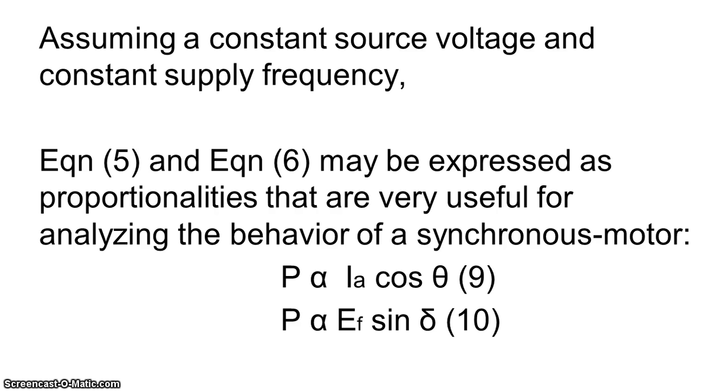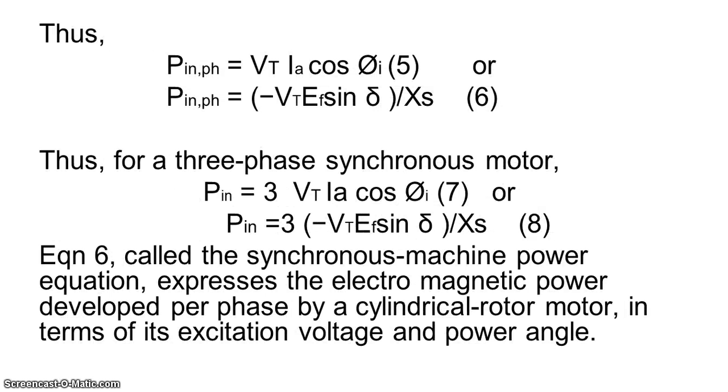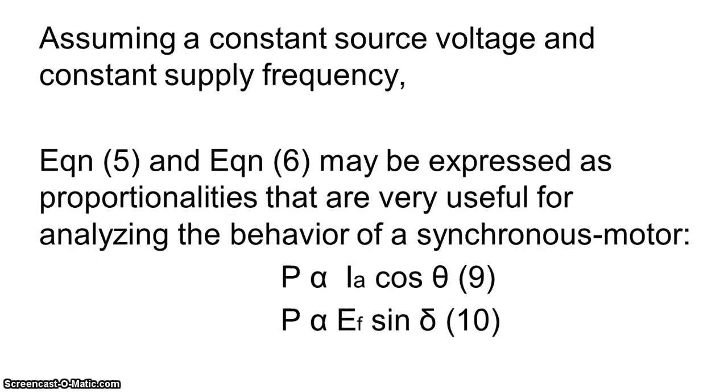So assuming a constant source voltage and constant supply frequency, the above equations 5 and 6, which give power input per phase equal to Vt Ia cos phi, may be expressed as proportionalities, and this is very useful in analyzing the behavior of the synchronous motor.